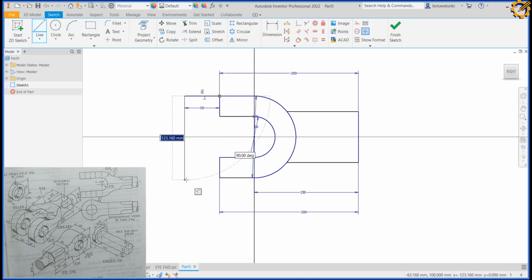Then close it right there. So then I just extend this all the way there, then extend this down there. Do you see that? So I'm going to pick another line. I'm going to just draw this line like this all the way down, and with my dimension, distance from this line to this new line, I'm going to make that 25.